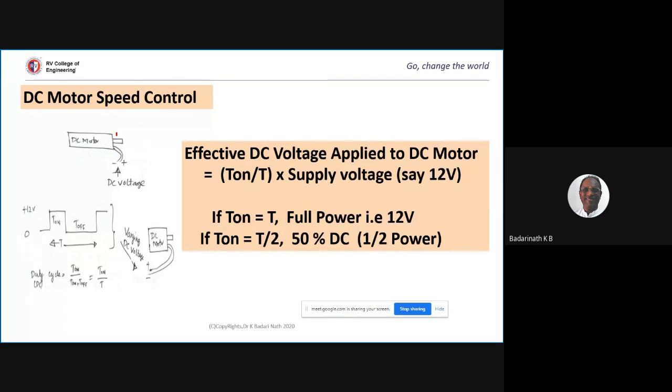But you cannot use the stepper motor for all applications because the cost is more and it may not be required. It may not run at very high speeds like a DC motor. So it depends upon the requirement of your project. Yes or no? You have to choose whether to use a stepper motor or a DC motor. Each of these motors finds a number of applications, and both are different. So you cannot use a stepper motor where a DC motor is suited. For example, the fan cooling the CPU on the motherboard, they are all DC motors. You cannot use a stepper motor for that purpose.